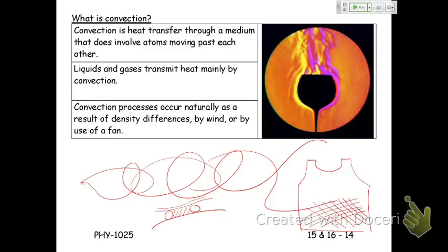They're going to conduct. And air is a really poor conductor. If it's not convecting, it's a really good insulator. The problem with air is it convects, and it's a real pain when it convects. So you get these weird situations where string vests rely upon the conduction of heat through air, not the convection. So very interesting.